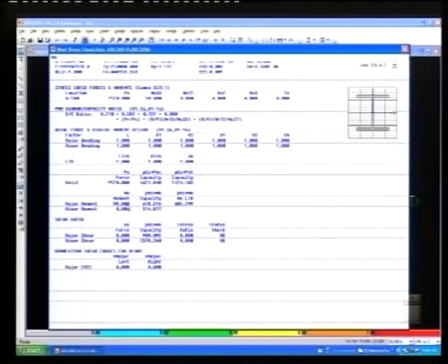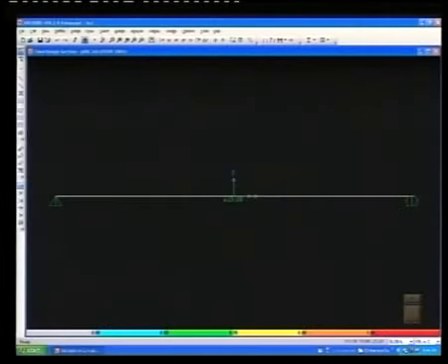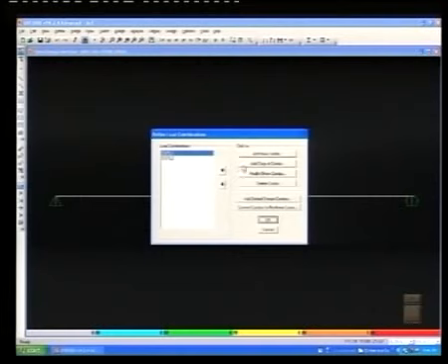The error is so obvious and you don't notice it. What is our bending moment? The ultimate bending moment is how much? 70. Now he's calculating it what? 98. Why? Because here we should have put define load combinations, define a load combination.